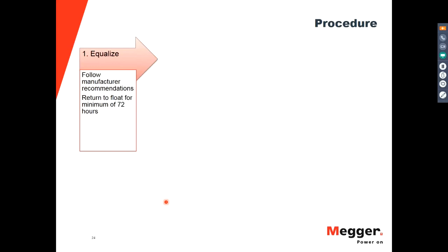This is one step that, if you want to reflect your maintenance practices, if you want to see if the battery really has the capacity that you are expecting due to the maintenance procedures, you want not to equalize. You want to skip this process.